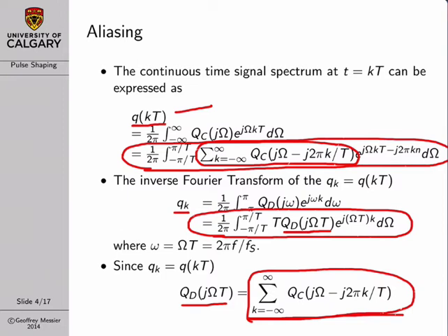If they do, this is what's known as aliasing. Aliasing can be avoided as long as the sampling is performed at twice the maximum frequency of the continuous time signal being converted to discrete time. And this is what's known as the Nyquist frequency, or the Nyquist sampling frequency.